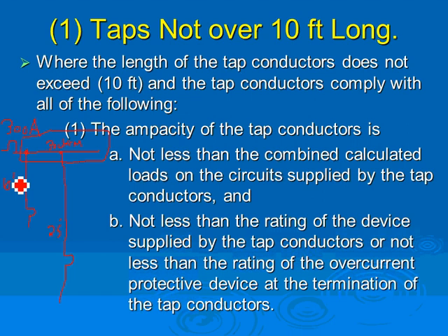Because what happens if you have a short circuit right here? You lose the whole system. The reliability of that tapped system is not the best, but it's cheaper, easy to install and easy to understand. You pull 10 feet from here to here, you put your circuit breaker, and then you put your load, let's say a panel or load here, and then a panel or load here, okay? This is 10 feet, believe it or not.